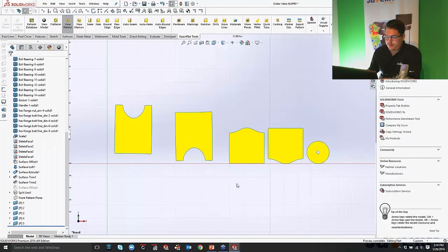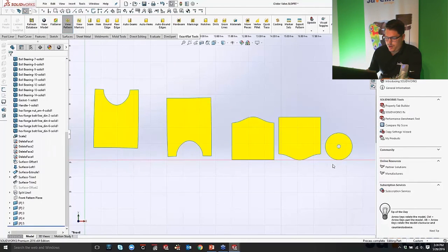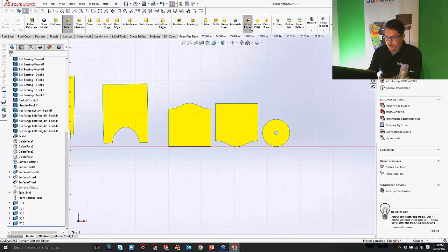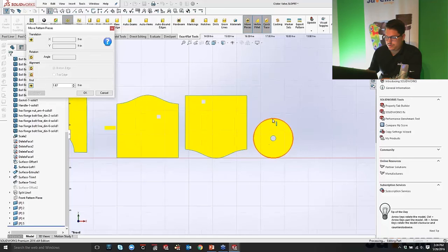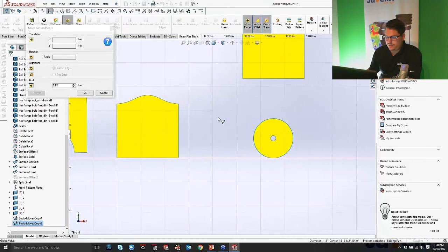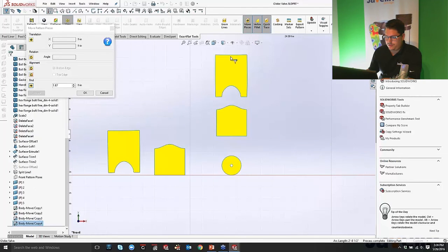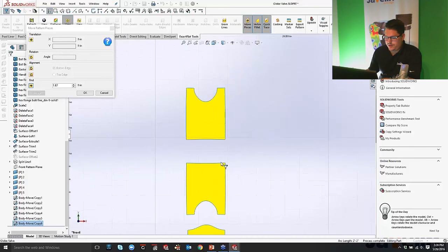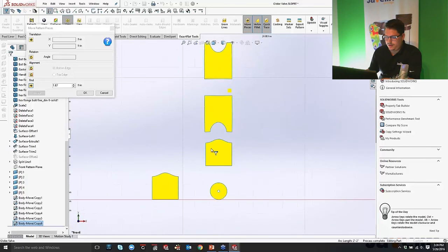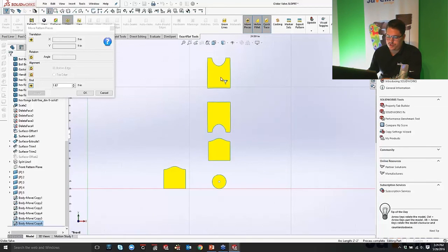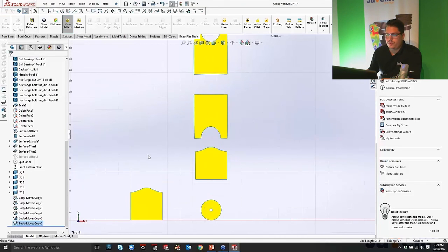So we can go to our flat pattern, and we're flattened out there. So now again, we can use those move tools. Oh, actually, that's a little bit far away. You can see the find tool in action here, and it automatically aligns all of our parts. It knows which edges connect with which edges. So again, I can go through. I can add my seams. I can add my hems.